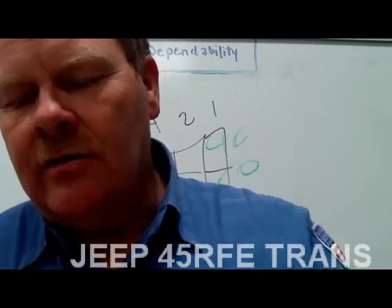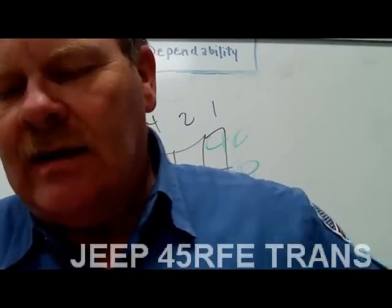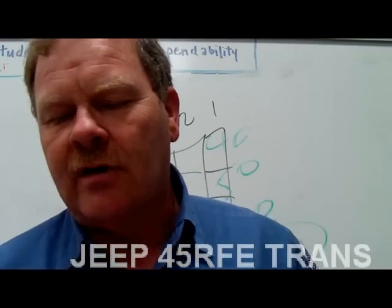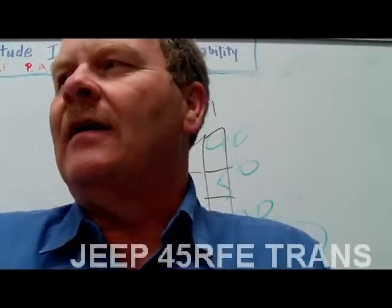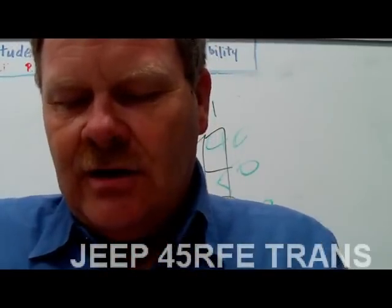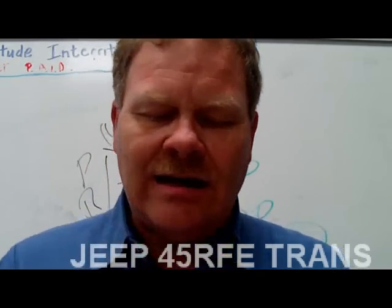Okay. Another direct input at the TCM is the line pressure sensor, which it uses to read main line pressure. That's a transducer. And because the transmission computer uses throttle angle when scheduling shifts, the throttle position sensor is hardwired to the transmission control module. Think about that. And the overdrive off switch cancels overdrive operation. It's also a direct TCM input. So you've got all these. Now you've got some indirect ones.